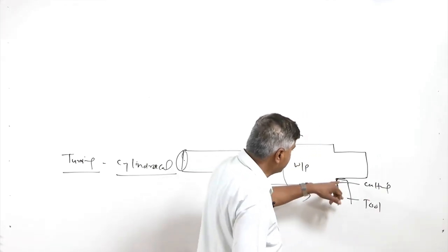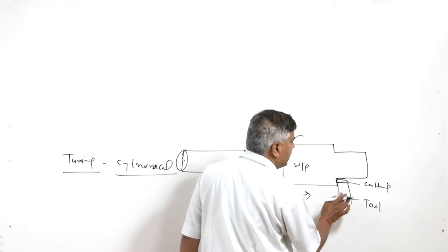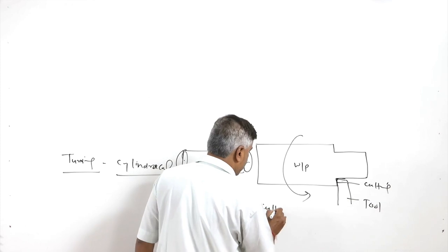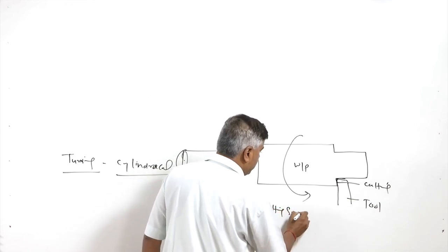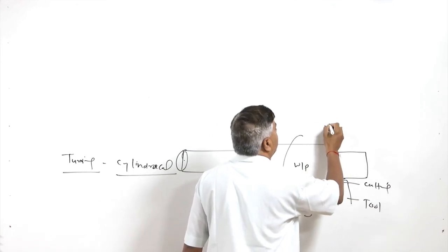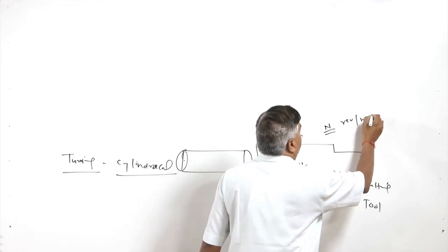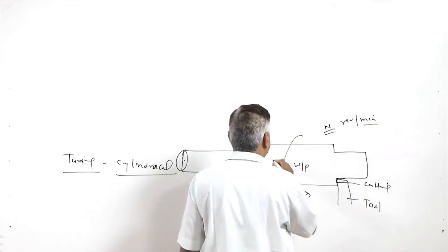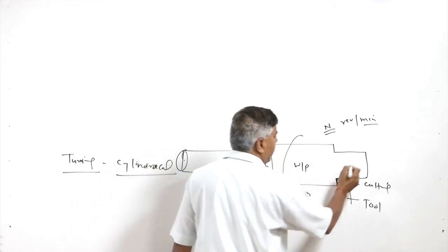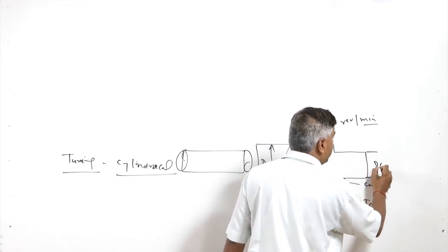Since the cutting edge is fixed and the workpiece is moving, the relative movement between the cutting edge and the workpiece is called cutting speed. Say the workpiece is rotating at n revolutions per minute, the diameter of the workpiece is Do, and the final diameter, the cylinder being produced after one cut, is Df.